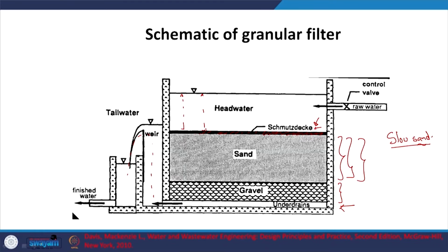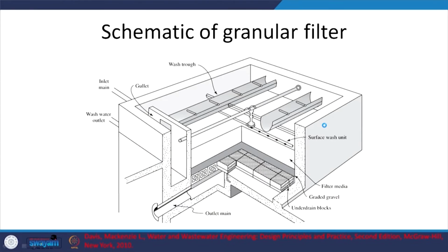And how do people clean it? People clean it by either replacing or scraping off this layer from time to time. So that is something to keep in mind, but again, very rarely used. The MIT courseware says something like 50 out of 50,000 filtration units in the US are slow sand filters. But again, what is the principle here? You have media, and then a layer developing over the top due to the screening action, and this layer will also have microbes developing there.